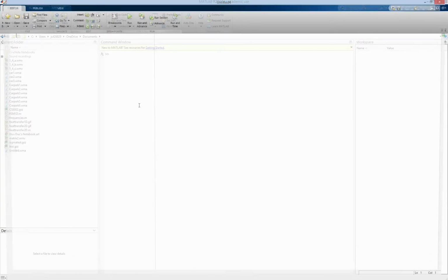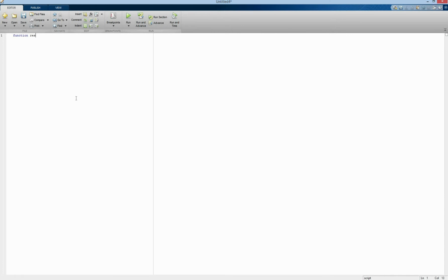So now we create a new function in 2D, which is based on the side of the plate, the number of elements in the x and y directions, Young's modulus, the Poisson ratio, and the force vector F. The scale value is the factor we multiply the displacement by to see it when it's so tiny. And the file name is the export file name when you want to export it later. However, in this tutorial, I'm going to use the figure only. You can do it by yourself.